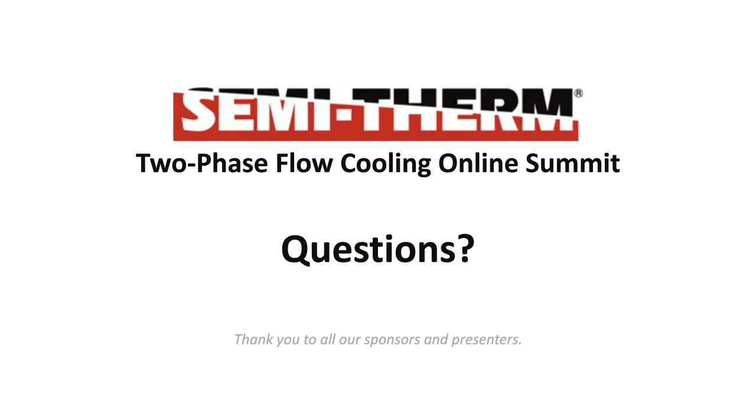Okay, we have a question here on is wearing of the PCM capsule possible? The PCM capsule, I assume that means the housing that encases the metal foam infused with the phase change material. There usually isn't any risk of wear on that external structure. And we have not experienced any problems with cycling or thermal fatigue over time.